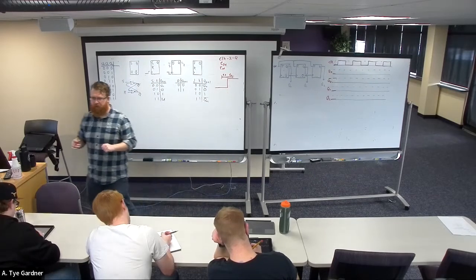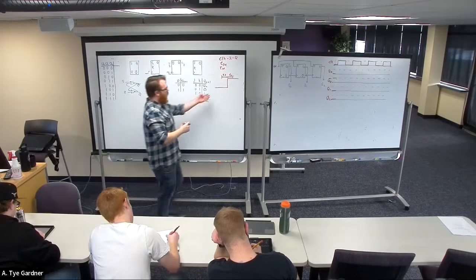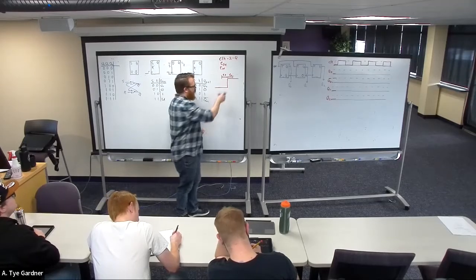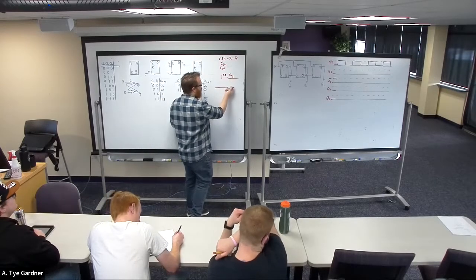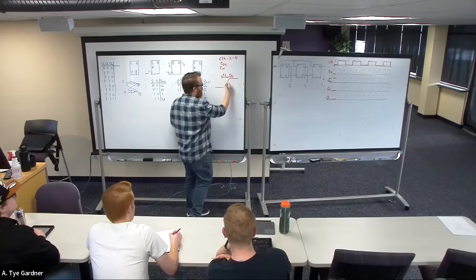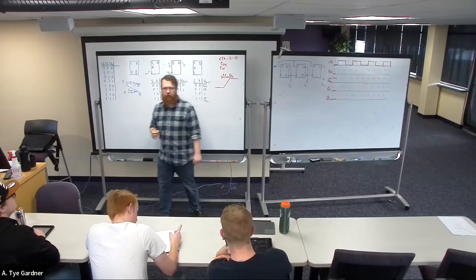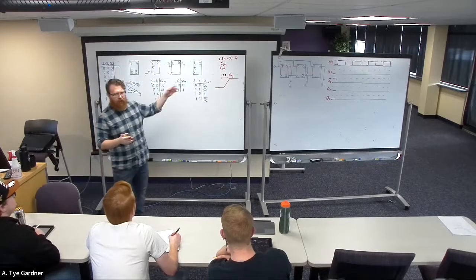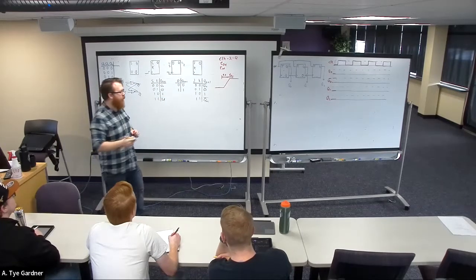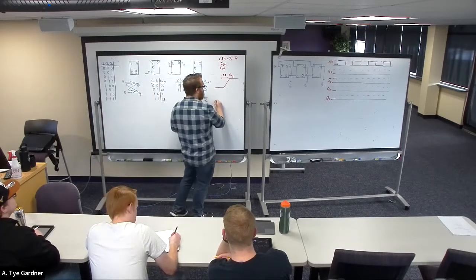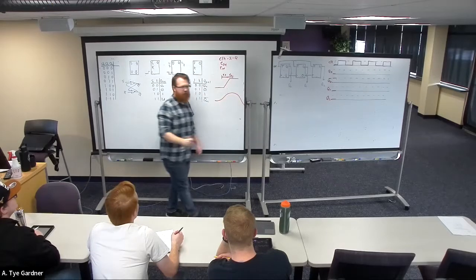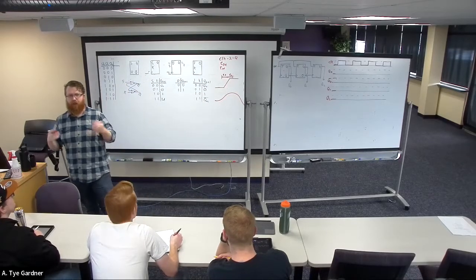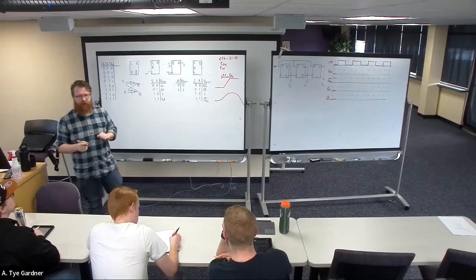Setup and hold time. And this is simply because a clock doesn't look like this. Not really. It looks like that. It takes some time for it to charge up. And the faster we go, the worse it looks. In fact, if you start pushing the edges of a clock, they start doing basically a sine wave, right? They can still work as a clock, but we need to be very careful with timing once they get there.